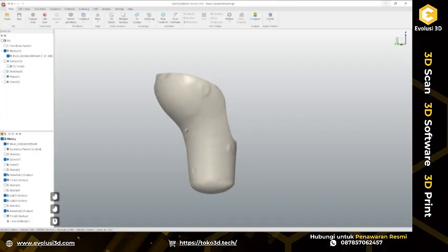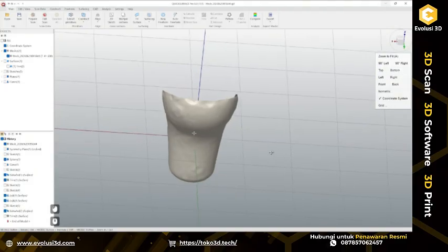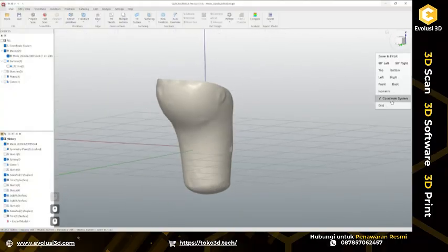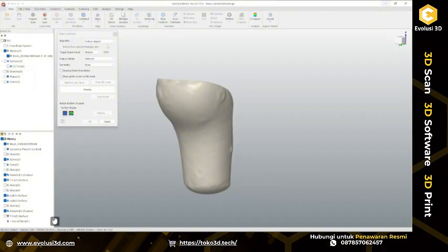So I'm going to split this scan data in the middle to have only one side, or actually I can leave it as it is right now because I have all my coordinate planes aligned, so it should work just fine. So let's go to auto freeform. I want it to be feature aligned, for example. The fanciest algorithm of auto freeform, of course.